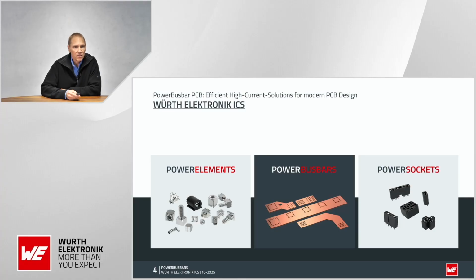Let us look at the Würth Elektronik ICS components team. We have three product groups. One are our power elements. These are high current connectors to distribute high currents into the PCB. You have the option of press fit, SMD, THT or THR, and we have also screwable and pluggable solutions.